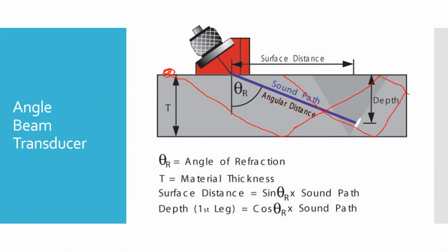So you see how that can get really complicated when you get these weird angles in there, where the sound starts bouncing all over instead of a nice straight out and back. So you really won't get much of an angle. If my probe was over to the left where I drew, you're not going to get much return right away. But now where they show the part there, where the probe is in relation to that simulated flaw, now it's going to get a return signal.